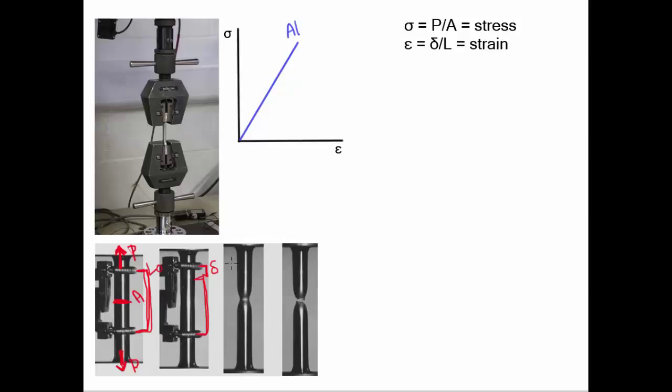Okay, so think of it this way. An object will strain under a given stress, and the more you stress it, the more it strains. Strain is a measure of stretch. Strain has no units because it is basically given to us as a percentage. If strain is 0.02, then the object has a 2% stretch. Stress is often given in pounds per square inch, but it's sometimes given in other units.